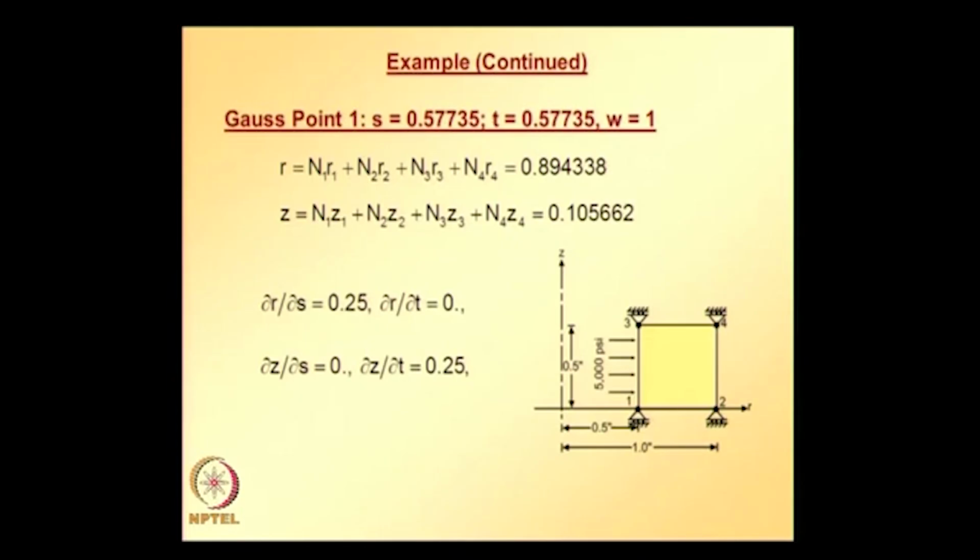Once we know all these quantities, we can easily calculate the A1, A2 and G matrices, and also the shape function matrix consisting of all the 4 node shape functions, which are required for calculating the strain displacement matrix, which in turn is used for getting the element stiffness matrix.